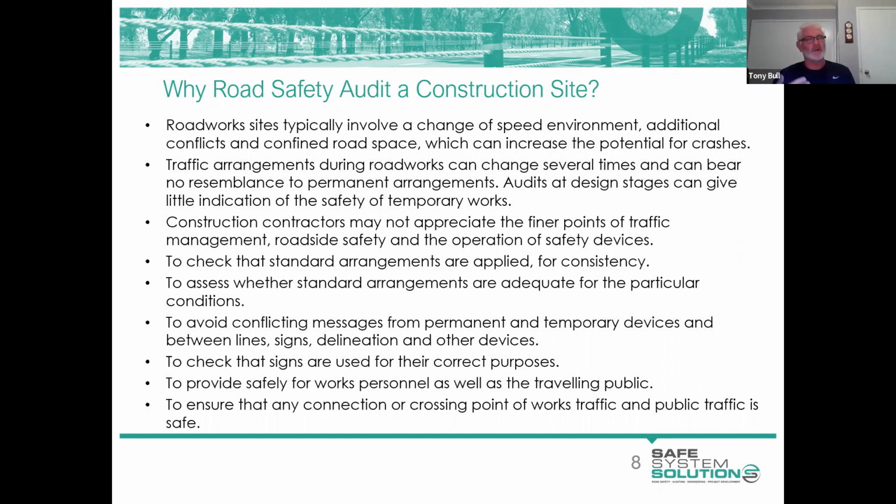So that's why they slowed the speed down to 40 km an hour. So at times, yes, you won't see the workers, but they are there. But a worker symbolic sign left up 24/7, it just shouldn't happen. It just puts the wrong message to the travelling public. We've got to make sure that the arrangement meets the conditions we're working to. Got to make sure we avoid conflicting messages.